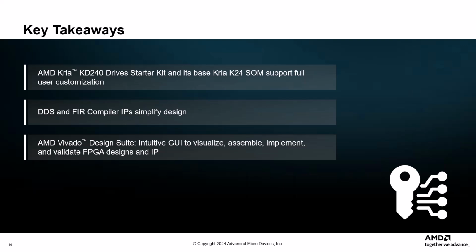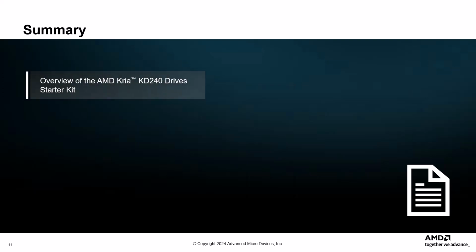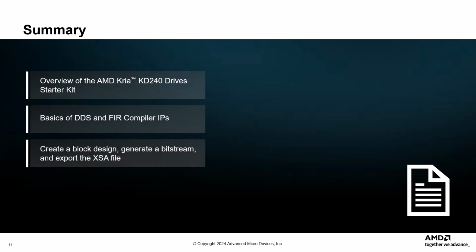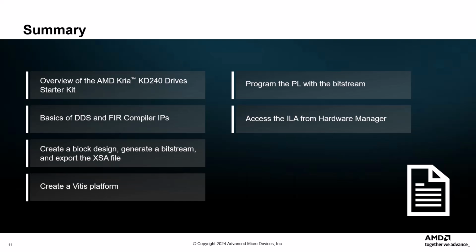To summarize, in this demo you gained an overview of the KD240 Drive Starter Kit and were introduced to the basics of DDS and FIR compiler IPs. You learned how to create a block design, generate a bitstream, and export the XSA file. You then saw how to use the XSA for platform creation, program the PL with the bitstream, and access the ILA block from the Vivado IDE hardware manager.